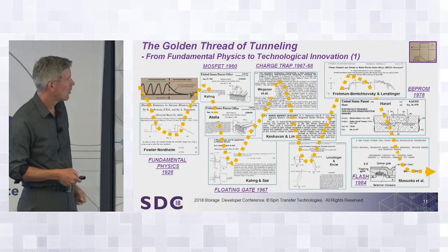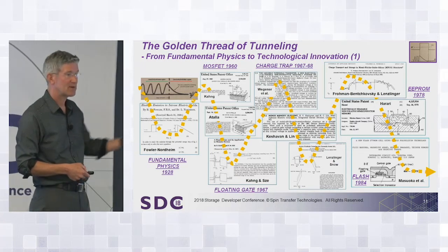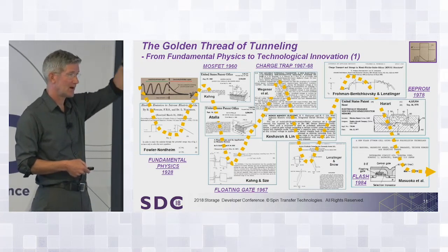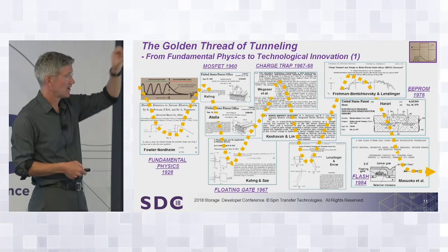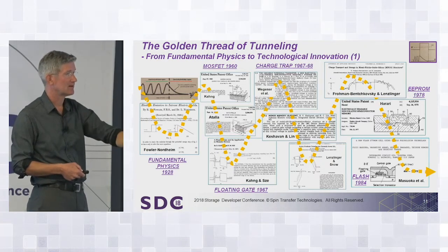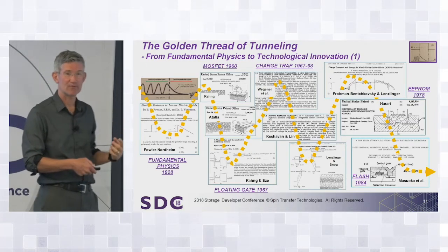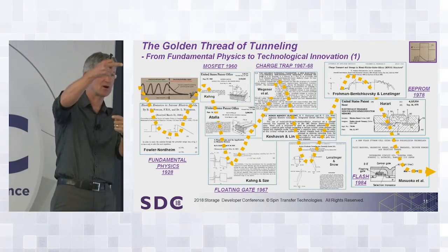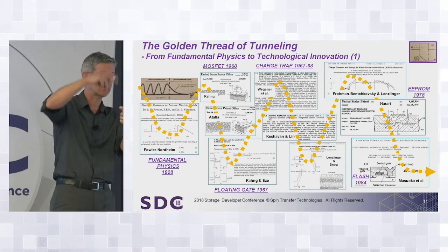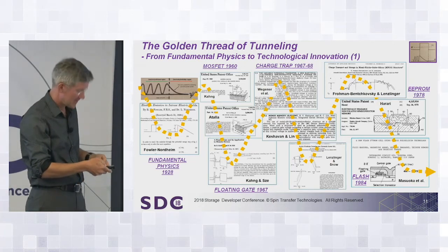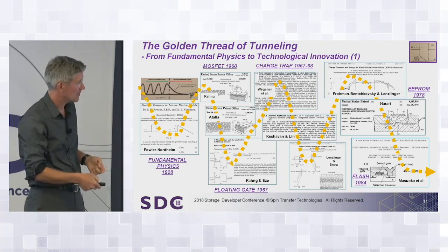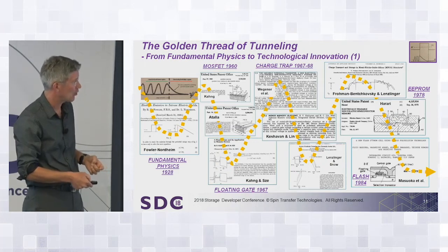Then you had a MONOS memory element, basically a SONOS device. So you had a gate, metal gate in that case, oxide, nitride, oxide, silicon. And they found, oh, we could change the threshold voltage of that device by storing charge, tunneling charge into and out of that nitride. And then Lenzlinger, remember that name, because I'll come back to that. Lenzlinger and Snow, describing the mechanism of Fowler-Nordheim for what Simon Sze and Kahng had been doing.